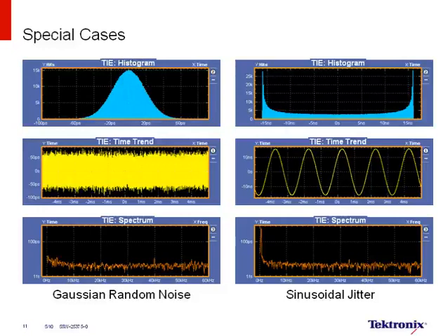So in this case, you probably see a spike, let's say around 30 kilohertz. If you have a 30 kilohertz modulation spread spectrum profile, or you might see 400 kilohertz power supply, switching supplies, or you might see, let's say, a gigahertz clock that's feeding through into your data signal. So these are very important views that allow you to diagnose and get a deeper understanding of some of the jitter root causes that may exist in your system.